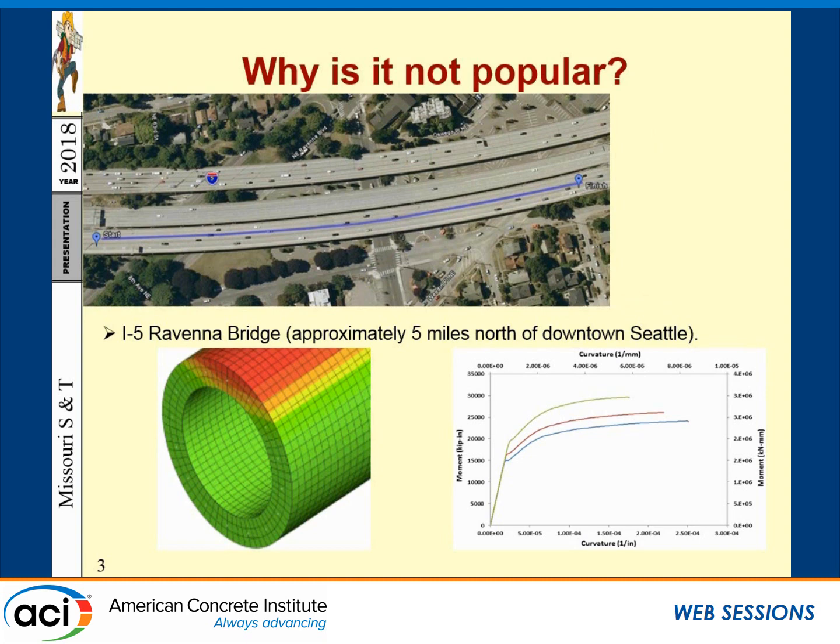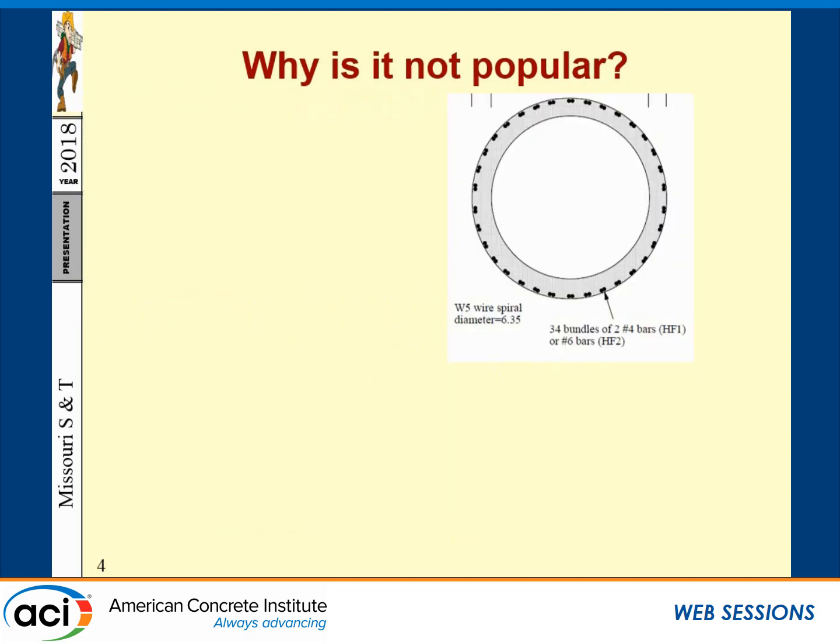We also did some finite element models. And as I mentioned, this is where you have the stress concentrations, and you see you lost almost 50%. This is the reinforcement bar over here. You lose approximately 50% of your cross section on the compression side because of, again, the strain.